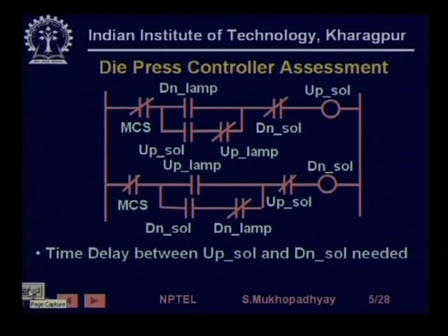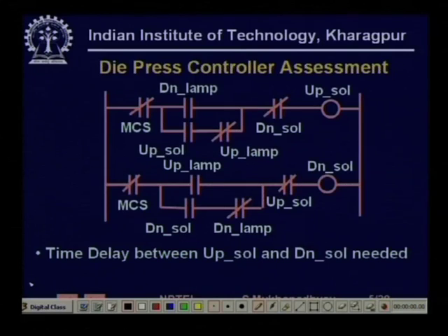Here we proposed an RLL program which used only the normally open and the normally closed contacts, the real input contacts as well as some auxiliary contacts and some output coils.